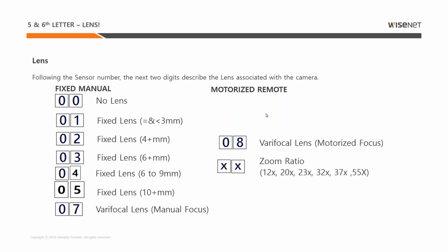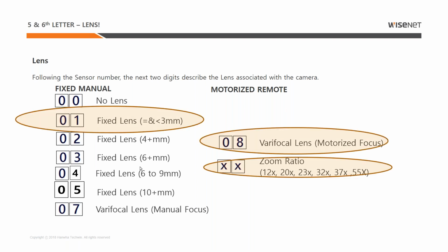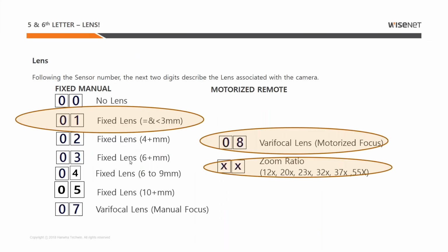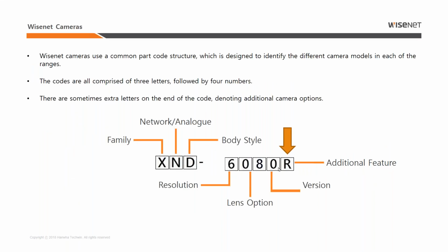Also, there are two types of adjustable lenses. The other numbers are mostly fixed lens. So for all entrances in any project, generally they use adjustable lens. If some cameras have a fixed lens, it will look the same from outside, but you should not use it at the entrance. Make sure some adjustable lens models are used at the entrance, because at the entrance you need to zoom in and make sure the view is correctly capturing the face. So look for these models for the entrances. Last is IR.